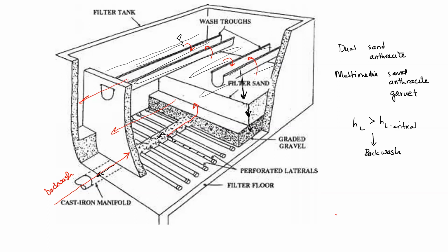Essentially, we are stirring up the sand in this backwashing. When fluidizing the material, we're dislodging material that collects in the filter trough.